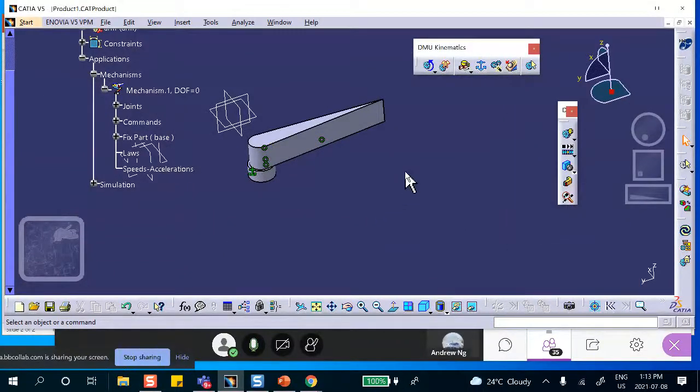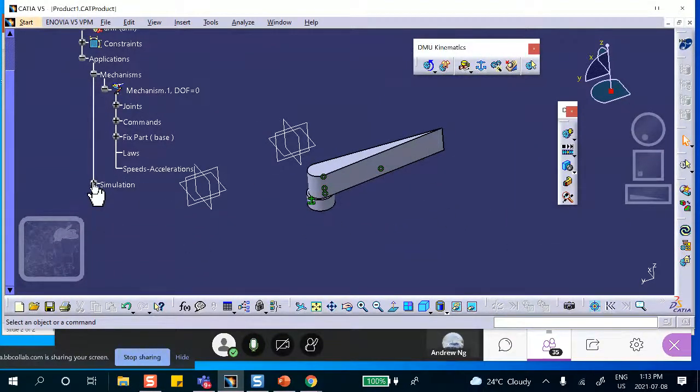Now, if you want to either create a video file for this, or you want to find the trace of this point. Trace means what path does it take? You need to compile this. You created the simulation, but you need to compile it. Without that, you can't do it. So you go to the next icon in that toolbar.